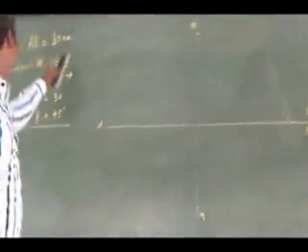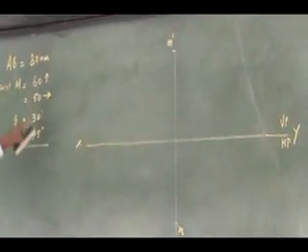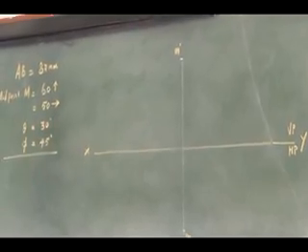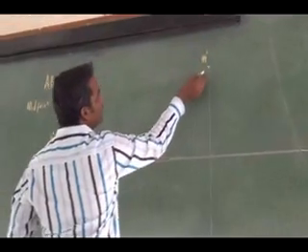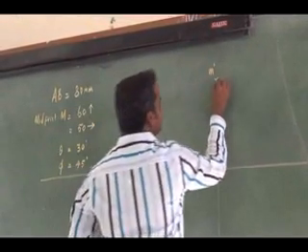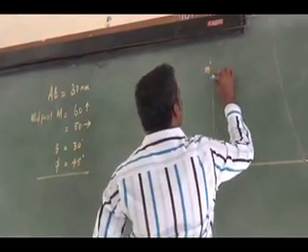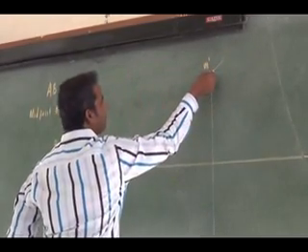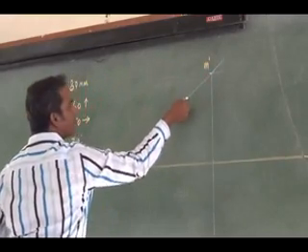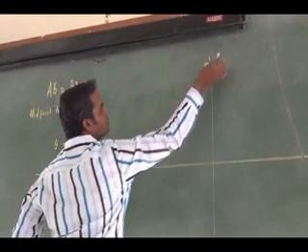As for the first step, I have to use the true length and the true inclination theta. What is the true length here? 80 mm. True inclination is theta 30 degree. So I can draw a 30 degree line here from midpoint projection. So I can extend it on both directions.